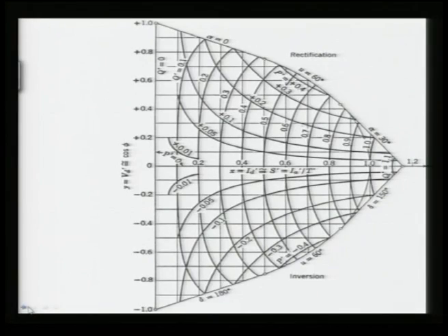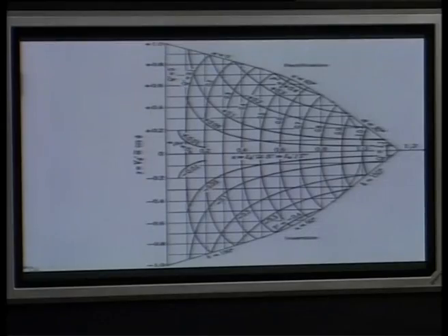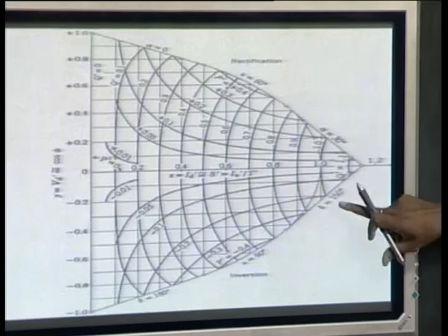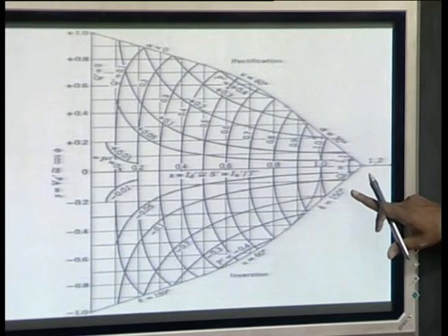So now I am going to draw this active and reactive power, as well as other quantities, on this chart. Before this, last time we were discussing that this angle is alpha here, and delta is 150 degree. This constant is similar to the other constant, because alpha, as I said, is not less than 30 degree. Here, delta cannot be greater than 150 degree.